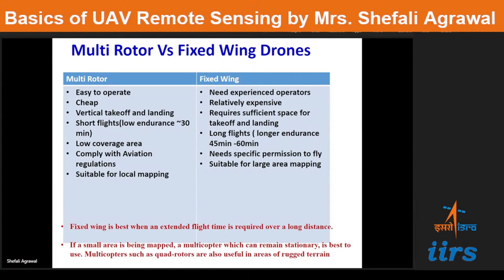They are slightly expensive because stability is more in the fixed wing, and it requires sufficient space for takeoff and landing. They have a longer endurance, longer flight time, so you can go up to an hour, and they require specific permission to fly. Since it has a longer endurance, you can fly it over a larger area and collect data in one go